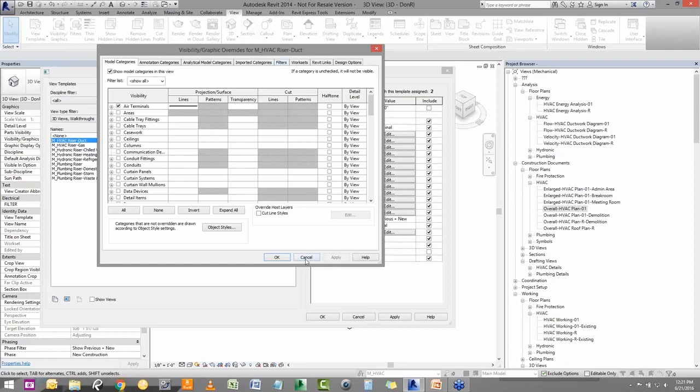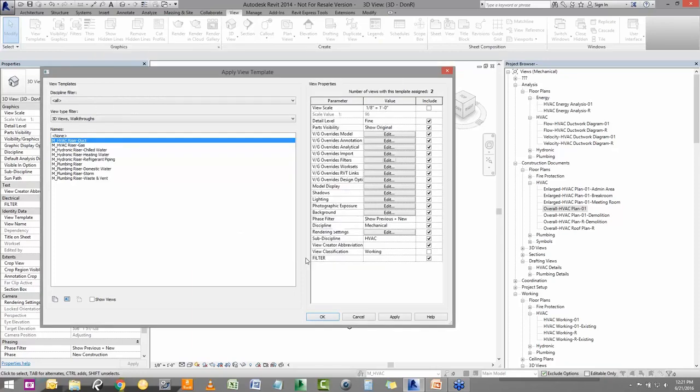Now I have these other filters created in here, not specifically for this view obviously, but because I may want them in other views. There can be a myriad of reasons why I may want to divide that up into a bunch of different views, mainly for exports. I like to export out of Revit with my different systems for the duct, simply because when I put them together in Navisworks, I can put my clash detections together a little bit faster than if I had just, say, for example, exported the entire MEP model and tried to set up clashes.